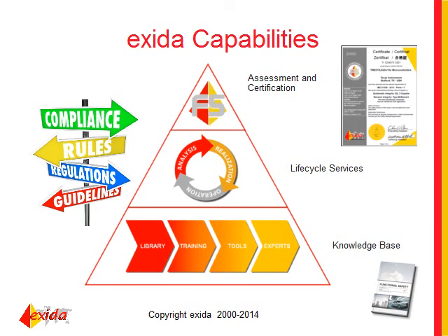So here's a question/comment. Can the max still be one if it involves operator response? So typically, IEC 61511 says you need to evaluate the reliability of the operator, and without doing a human reliability analysis, it's normally limited to a factor of 10, which would still be SIL 1.